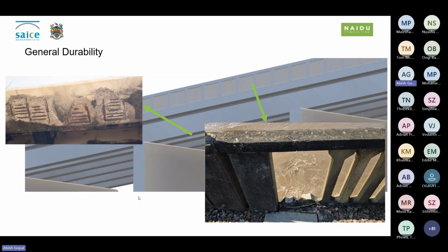In addition to that, the condition of the handrails does not make them fit for purpose. This same handrail system was also utilized on the roadway corridor side to provide containment for vehicles between the roadway corridor and the river. This is hazardous and is not compliant from an impact load perspective.